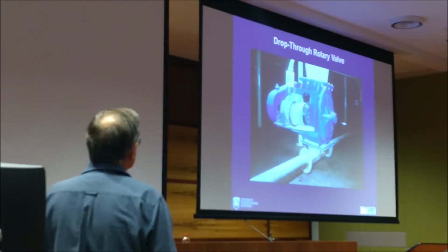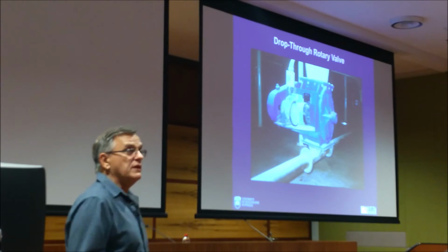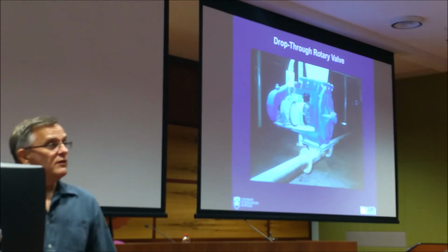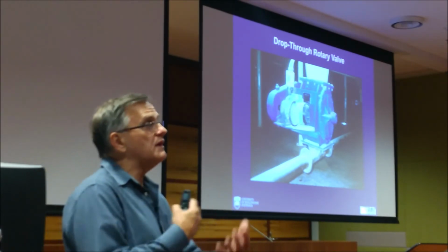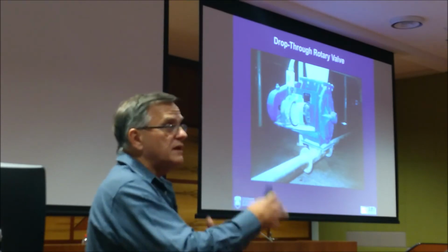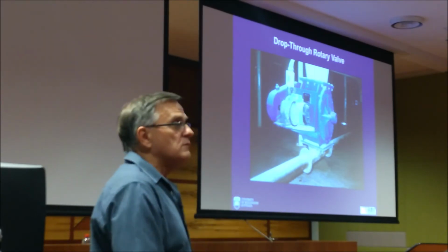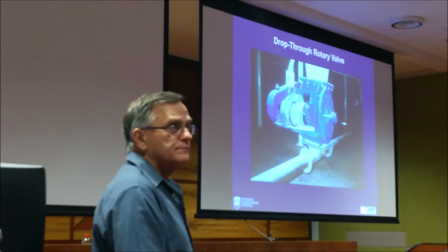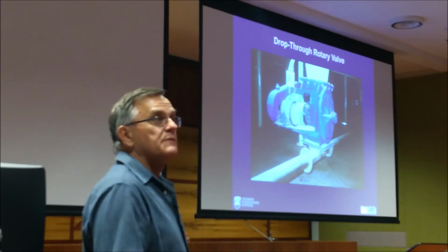Very simple device. You stop the valve, you stop your feeding. And so a rotary valve can give you continuous feeding and conveying, as long as the valve's rotating and there's material there, 10 tonnes an hour until something stops.